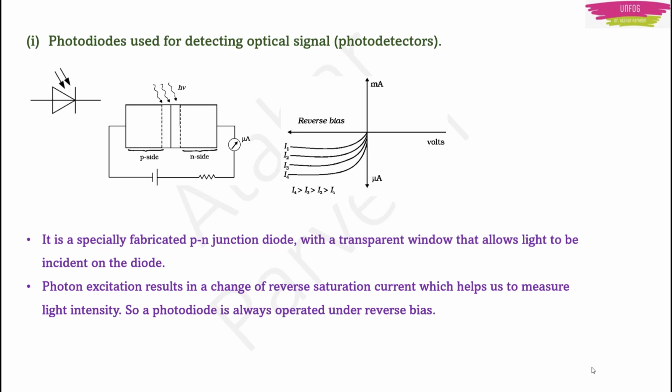So one question can be asked like this: photodiodes operate at? So the answer must be reverse bias condition. So what is the difference between a PN junction diode and a photodiode? Photodiode, being a PN junction diode, is not operated at forward bias. Remember, the PN junction diode was operated only in forward bias, but the photodiode is operated in reverse bias. What is one more difference? One more difference is that these photodiodes are optoelectronic devices. If light falls on it, then only it will work.